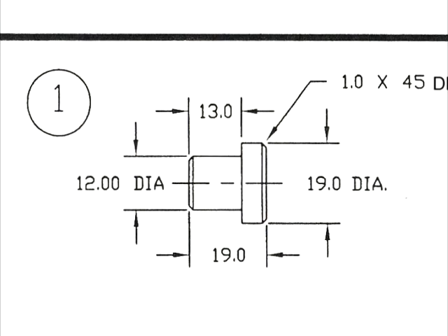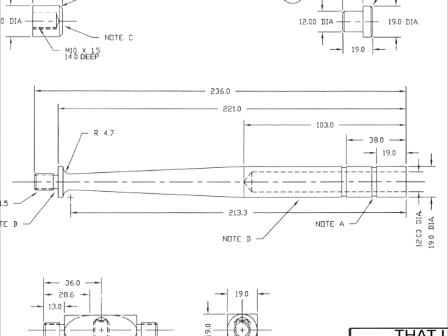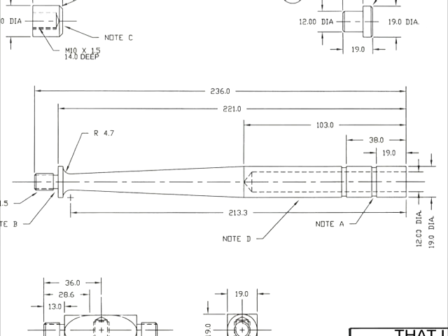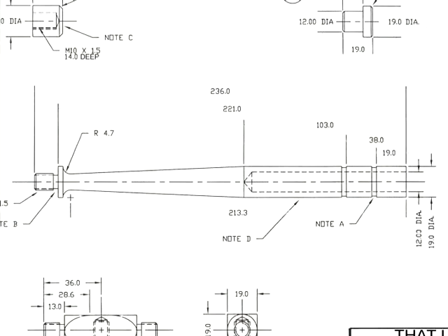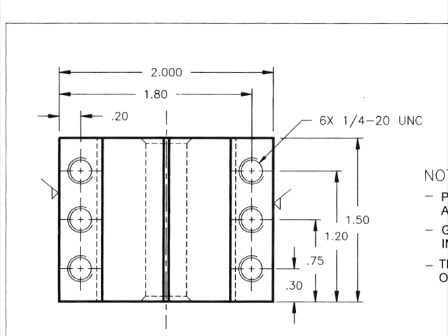Removing the dimension lines from the drawing of a small part doesn't confuse things that much. That's mainly because the dimensions are quite close to the extension lines already. However, on a larger part or on a looser drawing, our dimension lines can really help to clear things up, as we can see with this hammer handle example. Now, you don't want to end up with a jumble of lines that just confuses the drawing even more. So your dimension lines should be stepped or positioned in a way to avoid overlapping lines.